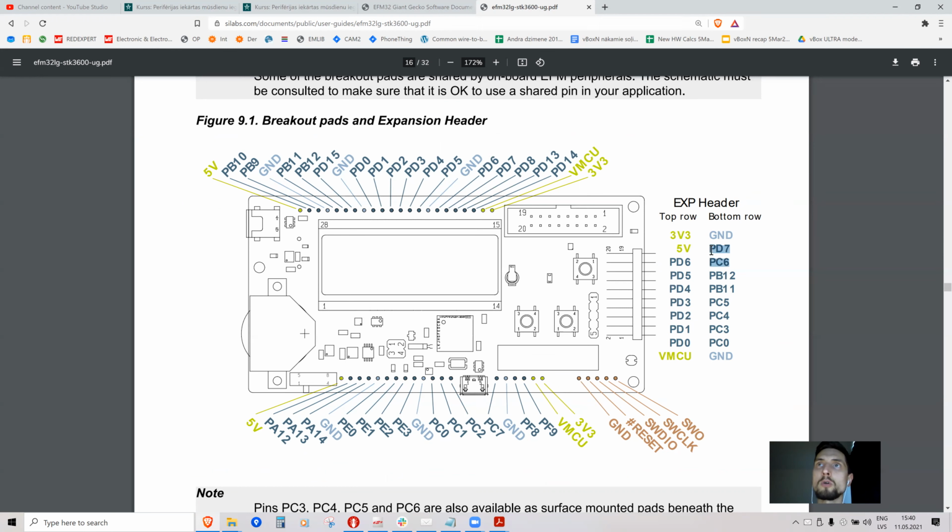So we have a short circuit jumper between port C6 and port D7, so that the output of light sensor is connected to port D7 of analog to digital converter, and we can sample the signal. So on your development kits, please leave this jumper on. Do not remove it. It's between these two pins, and let's leave it there.